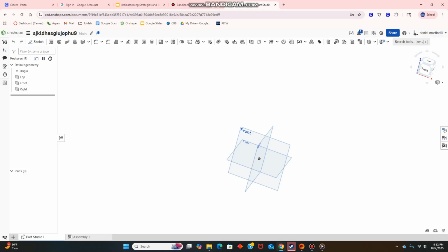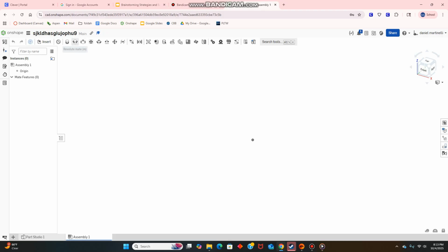Okay. And then assemblies, you will have all of these mates up here. So these mate connectors are very useful. Fastened mates are just for fastening two parts together, and there's no degree of freedom between the two entities. Revolute mate is if you want one thing to rotate around another.